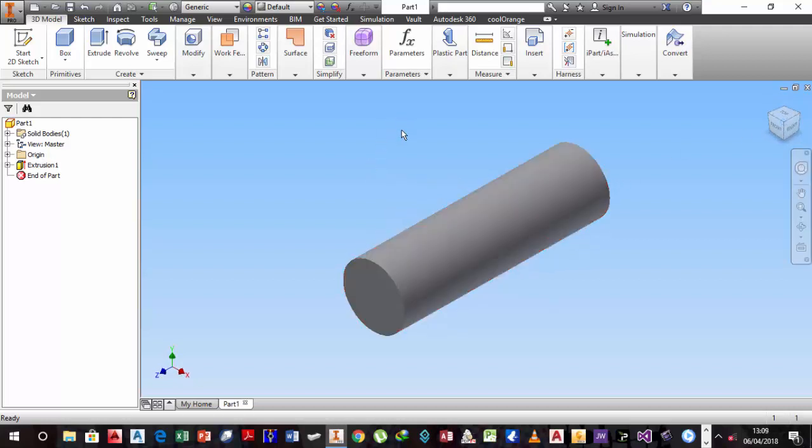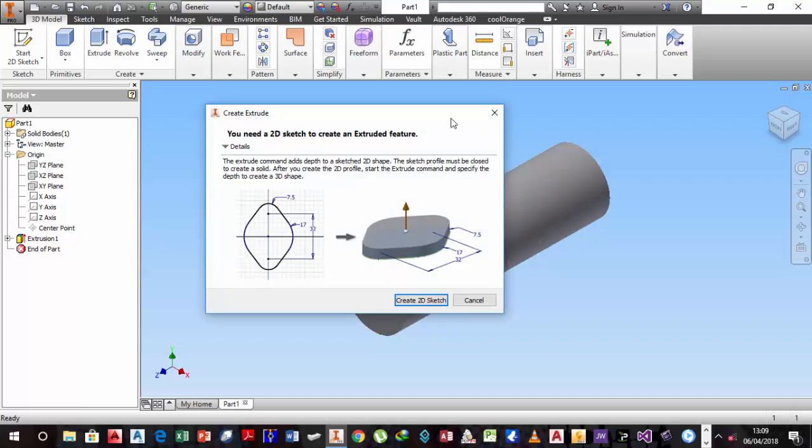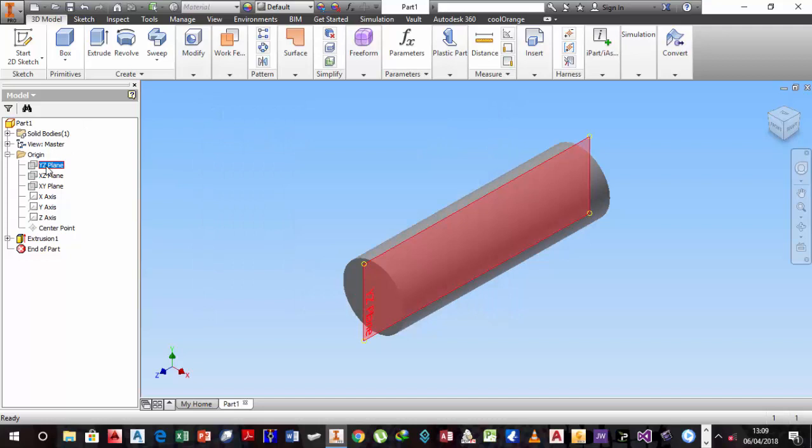The next part of our drawing now is to see how we can get our rotation axis and also a little triangle, not triangle, a rectangle. So let's go this way. You go to origin, get a drop down, trace your YZ plane, right click on it, and click on visibility. Okay, this will now show.